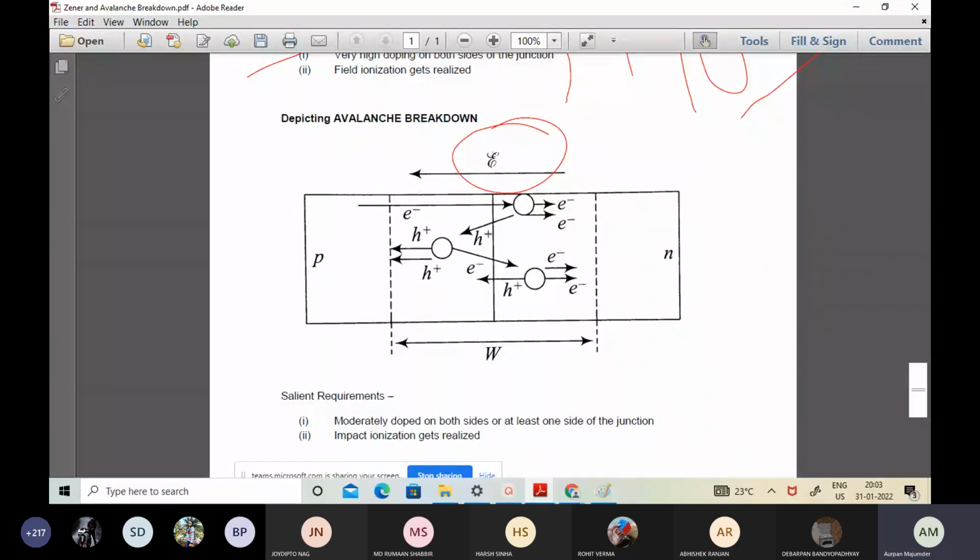If you think about normal diodes, not a Zener diode, normal diodes do have avalanche breakdown more or less above 8 volts. Very few diodes have avalanche breakdown less than 8 volts. To be very frank with all of you, if you are encountering in any kind of a diode a breakdown potential, let us say you are applying the reverse biasing voltage and you are observing the corresponding current flow to the circuit.